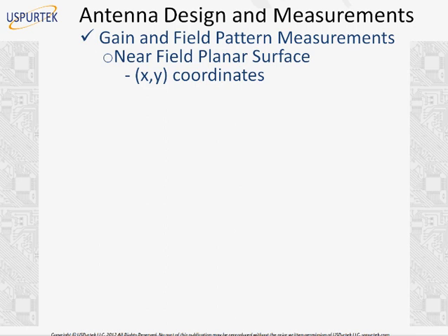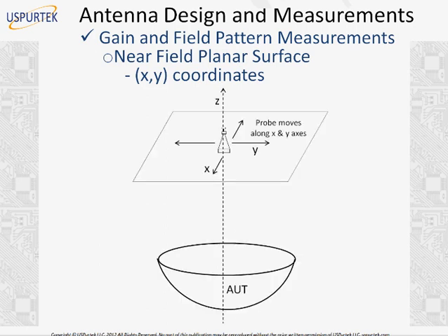But still there is an alternate technique available which has been devised to overcome the limitations of the open area test range or anechoic chamber, because they are expensive sets of equipment too. So if you have the software available that computes from near field to far field, you could use that technique too. But in general, we will not use near field measurement. It's not recommended to measure in the near field unless you have the conversion software available, which will convert these measurements into the far field pattern.